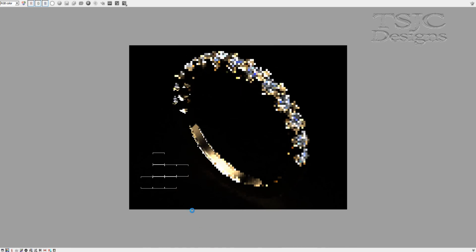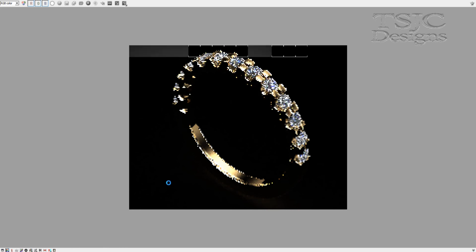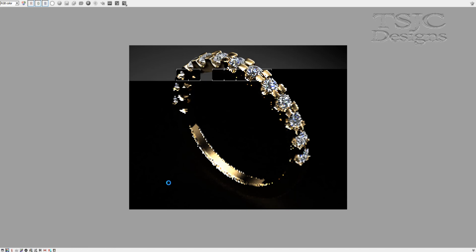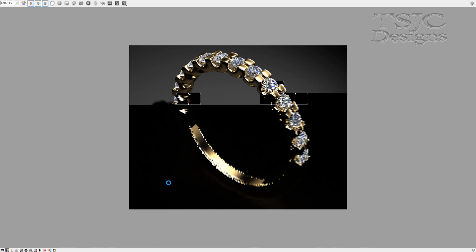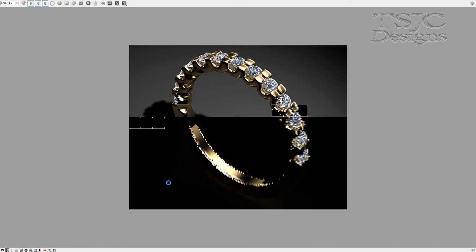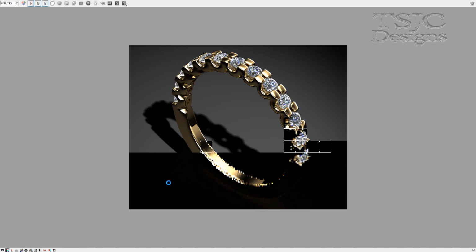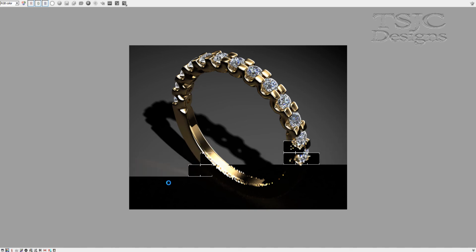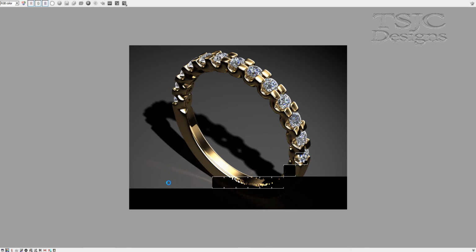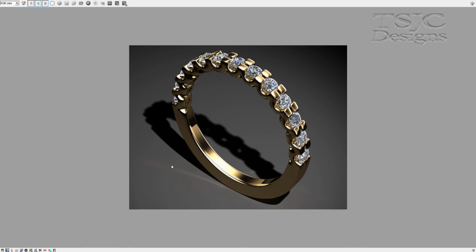It's the caustics, that kind of gold reflection you saw there is, I believe, caustics. Pretty sure it's caustics. So you'll notice that this is far quicker, and it's because we've turned off that depth of field. Now you can do depth of field in Photoshop, you can do depth of field in Matrix through the render, which takes ages, or you can do depth of field through the render editor, which is worth exploring. So you do get this nice caustics effect here, which is worth playing around with.